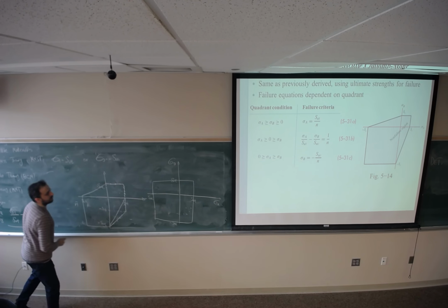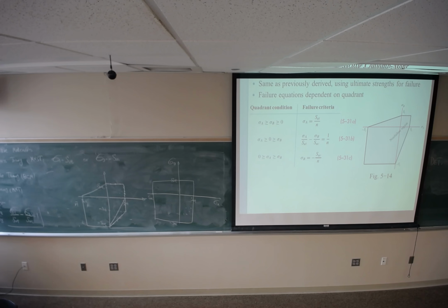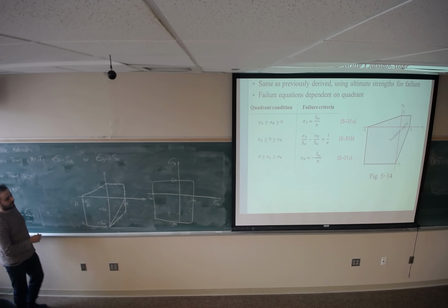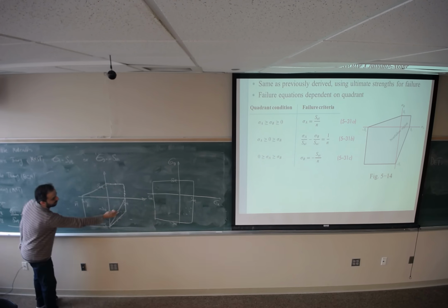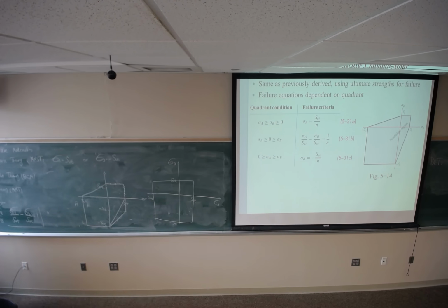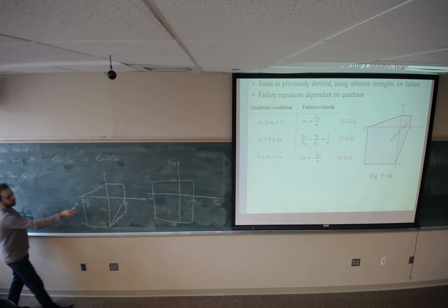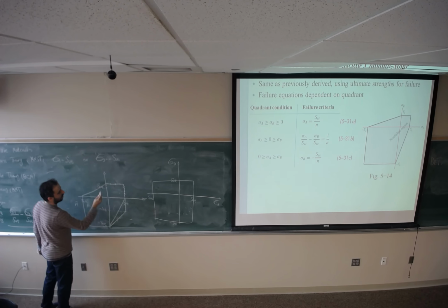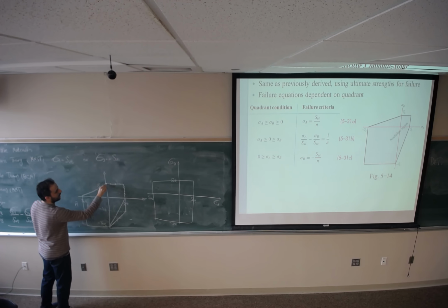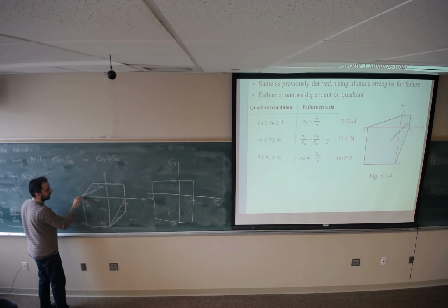This theory is going to be modified Mohr theory. It's less conservative than this one, but it's going to have a better fit for experimental data. Similarly here, SUT here, negative SUT here, extend this line, and then connect this to this one.